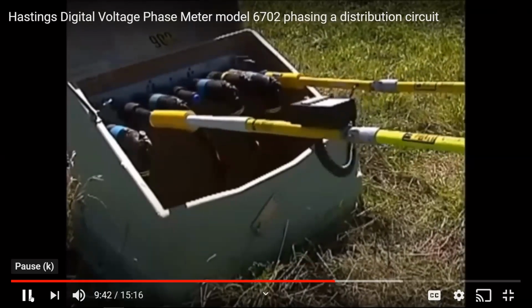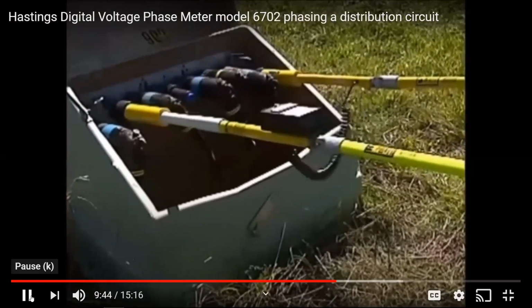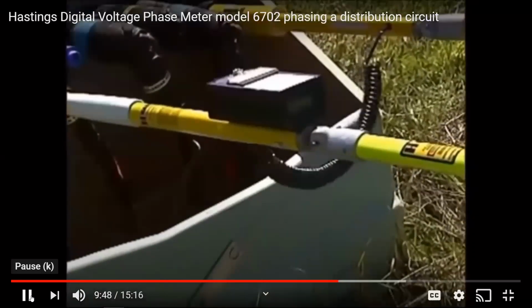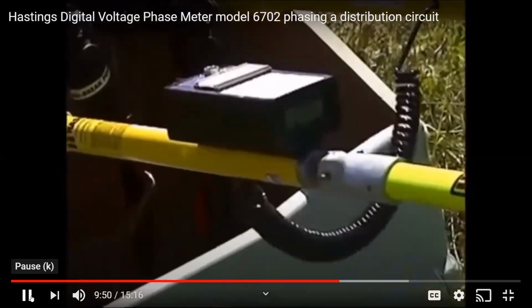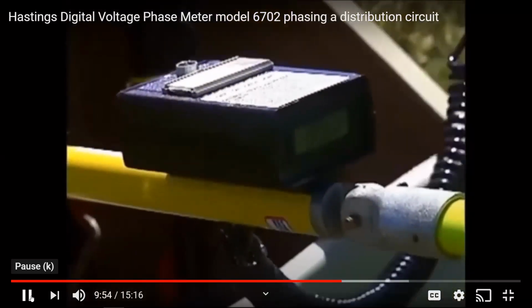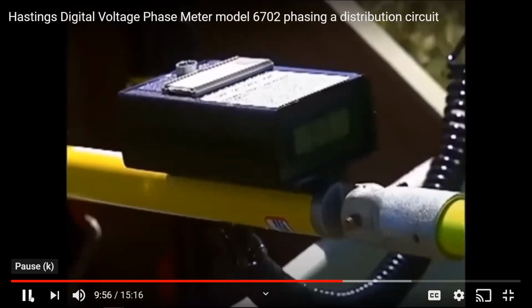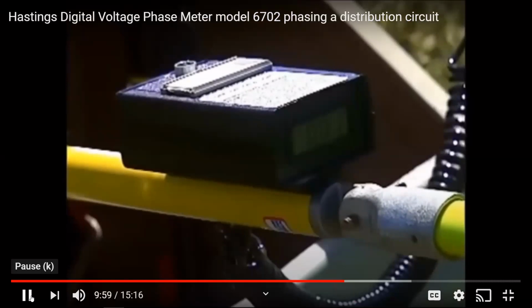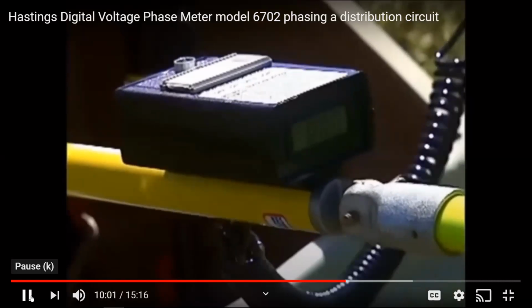And when you're ready, I had good current flow to begin with. It's reducing. It's charging the cable. The cable's accepting that charge. I went from a full reading to a 0.1, and to 0. That is a good underground cable.